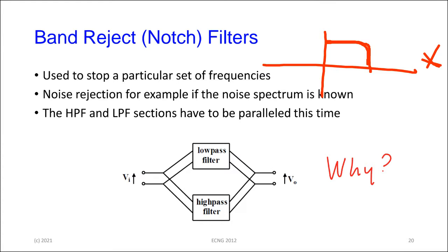If we run it now through a high pass filter whose cutoff frequency is here, you're not going to get anything, because we already lopped off everything below that. So there's nothing for the high pass filter to let pass through. So all you're going to get is low pass filter behavior. And it doesn't matter if you swap them, because all you're going to do when you cascade them like this is create the bandpass filter behavior, which is what we did before.